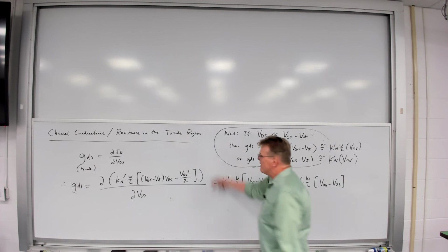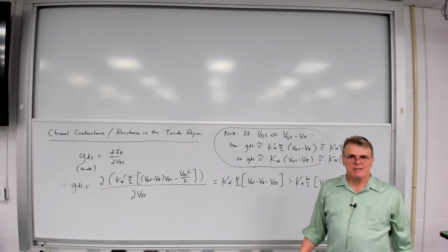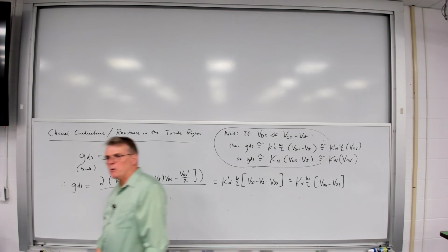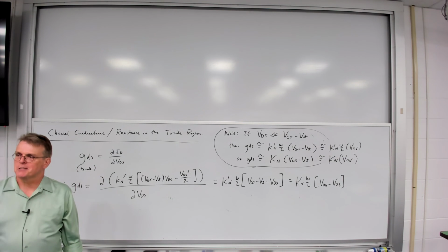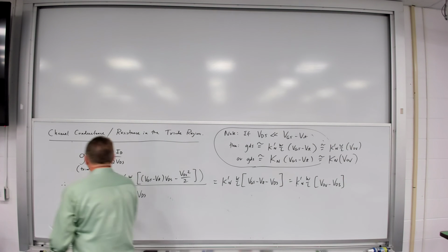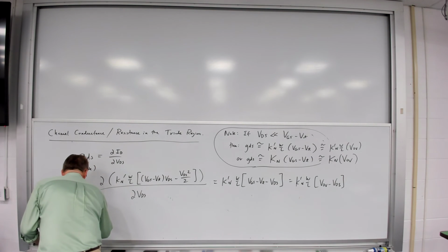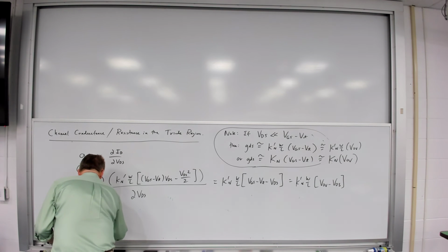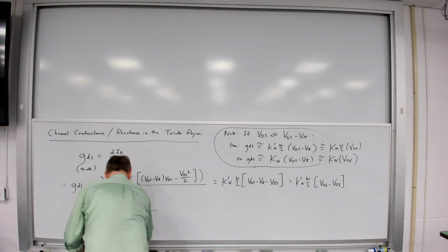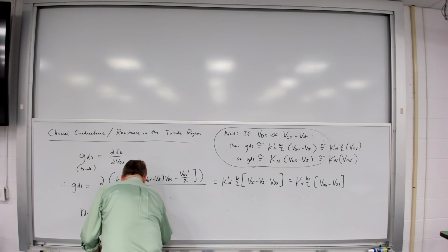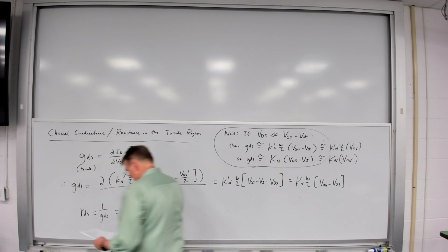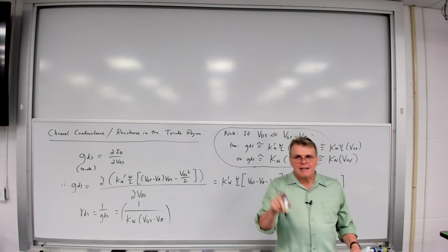Now I've defined conductance, because conductance was easily calculated given the fact we had a drain current equation. What's the resistance? Inverse of conductance, exactly. So RDS is just going to be equal to the inverse of the conductance, which will be equal to 1 over Kn times VGS minus Vt, assuming VDS is small.